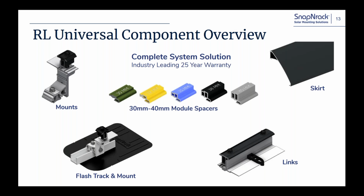And what that does is, when you clamp the skirt down, that provides that initial height set for the rest of the modules to be installed. So if you can install 35 millimeter modules, you'll take those blue spacers and clip them onto the links or mounts in the very front, attach your skirt, and as you clamp down onto the skirt, it'll create a space of 35 millimeters for those modules to be sleeved in on the uphill side of that clamp and link.